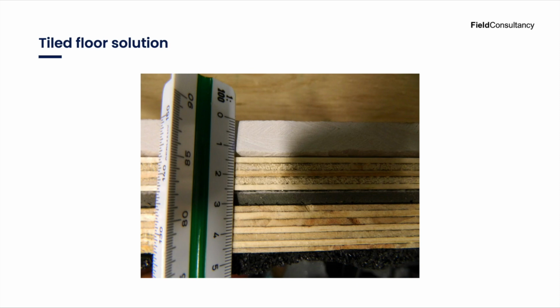And here's a photograph showing the overall thickness of that tile build-up. As you can see, it was about 54mm. 60mm was the maximum thickness that we were allowed to go to with this build-up, so we met that criterion for the design. And you can see the close-up picture of the tile surface, the plywood layers, the Regupol resilient layer in between, and then the dimpled Regupol resilient mat at the bottom.